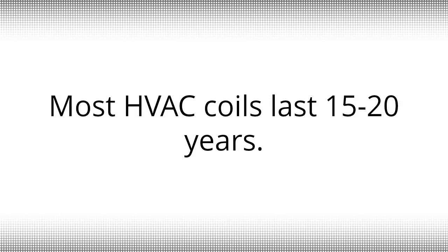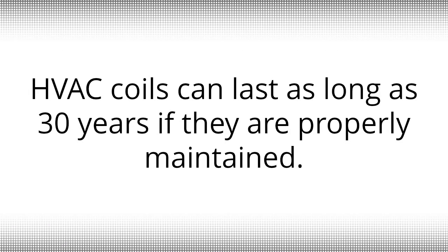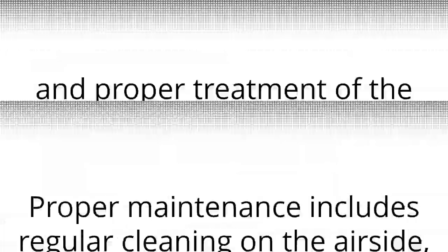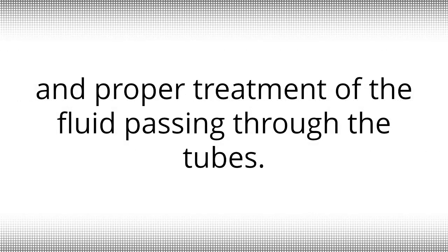Most HVAC coils last 15 to 20 years. HVAC coils can last as long as 30 years if they are properly maintained. Proper maintenance includes regular cleaning on the air side, and proper treatment of the fluid passing through the tubes.